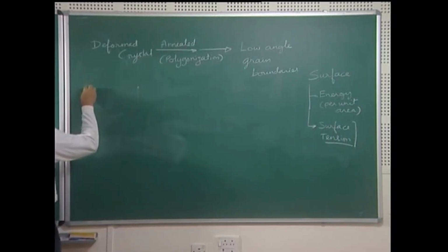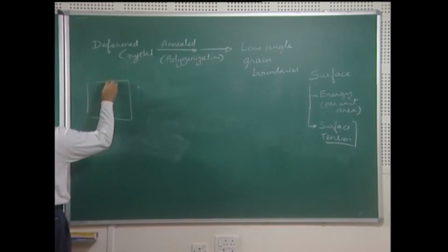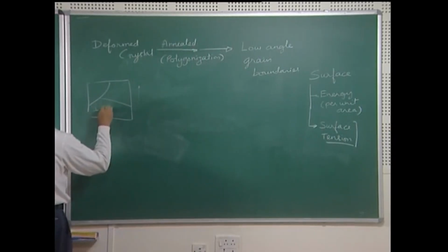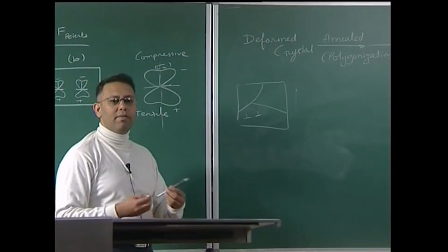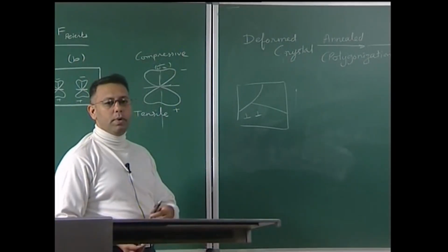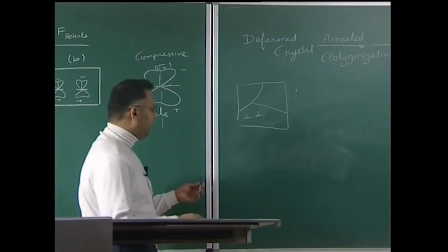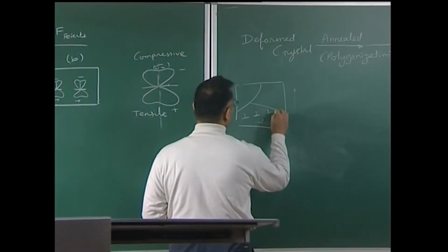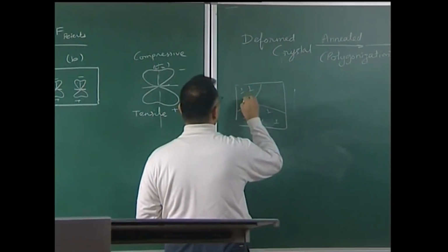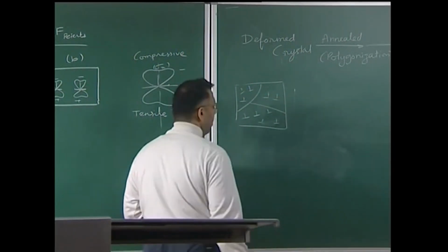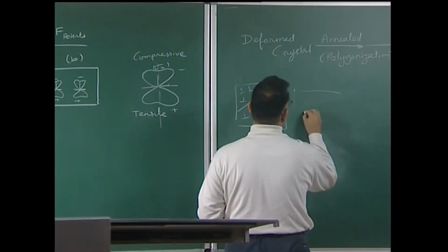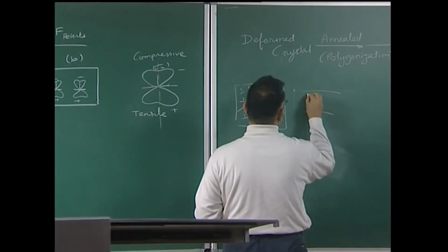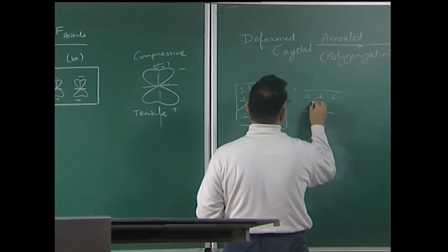Actually, if I now consider a polycrystalline material, and I am just going to draw some crude schematics here, there are going to be a lot of dislocations, and of course, though I am using a symbol for an edge dislocation, a general dislocation in a crystal could actually have a mixed character. It could be partially screw, it could be partially edge, and therefore, it could have any general character. So, I am just drawing some schematic showing these dislocations. And if I am looking at a single crystal, a single grain within this could get bent because of the presence of these dislocations.